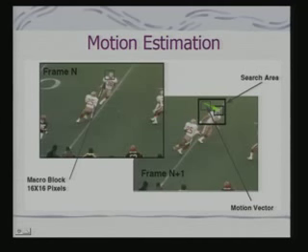That means, the data in the current frame I can predict from the previous frame. And what do we store in that case? We store these shift vectors and the error. The error is stored again like a JPEG image. We apply a DCT to the error, then we do quantization, then we do entropy encoding